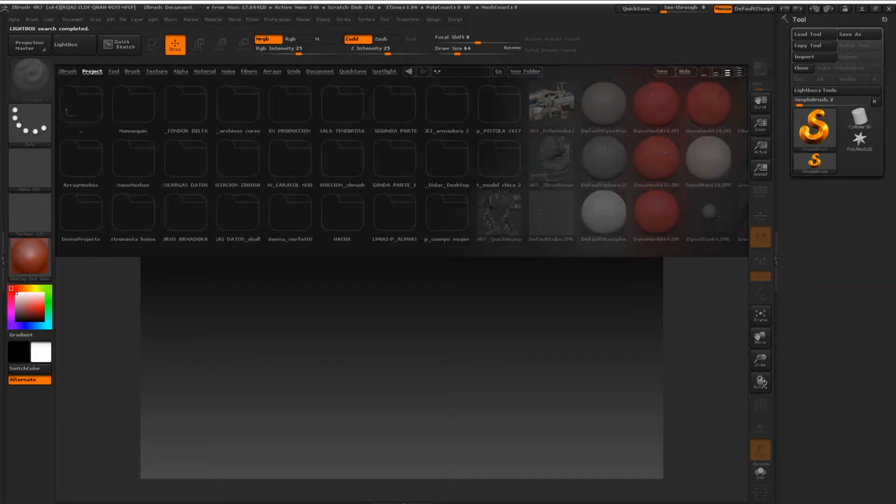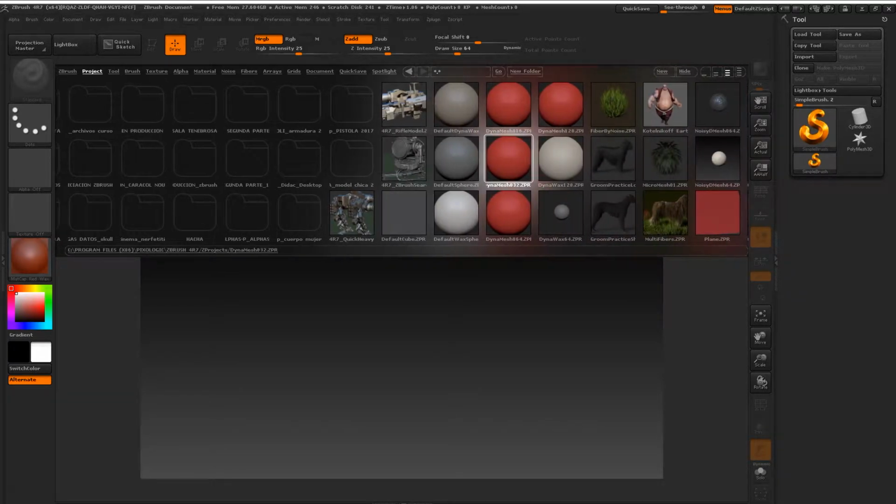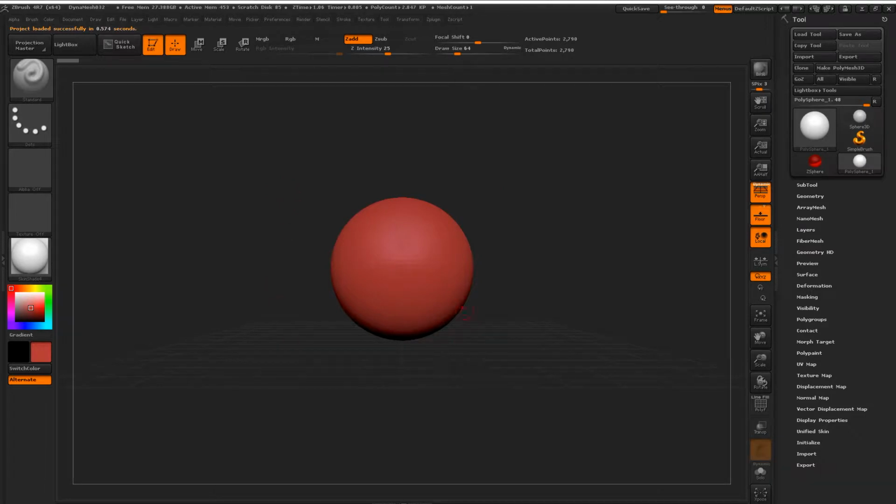To start with, we'll put in a sphere. This one, to start the program. As you can see, this is just a preview. We don't have split views, so to start, what we can do is take out the perspective with this button here. Normally, with ZBrush, we would work without a perspective and later look over the work we're doing, activating the perspective. Here we have a line with different elements,